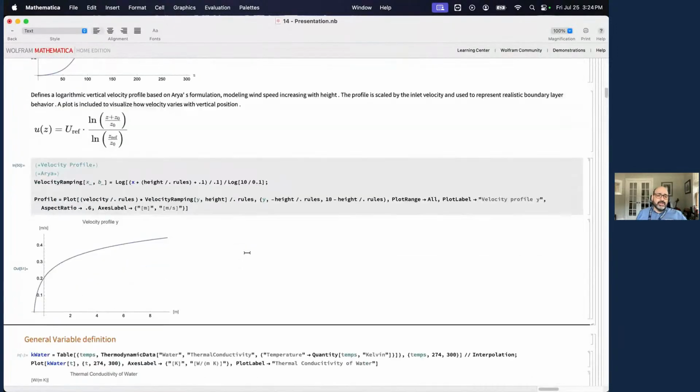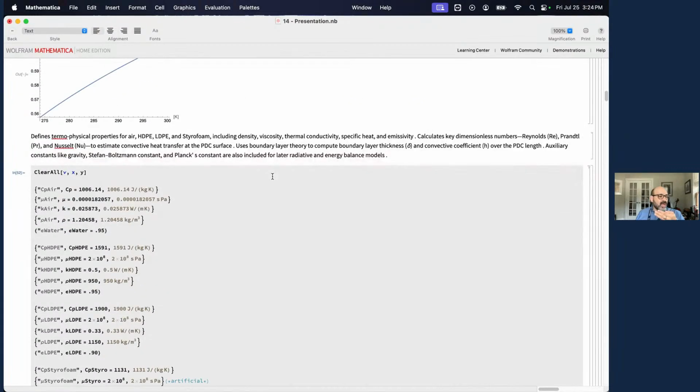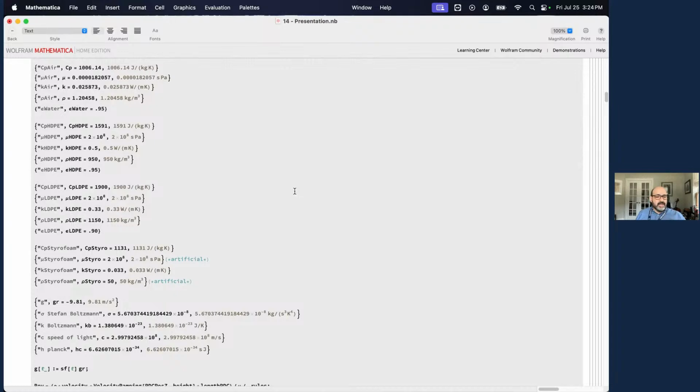Now, the other technique that I use is that I broke this down into several steps. First of all, solving the Navier-Stokes equation. Second, solving the heat equation. Third, solving the radiation, then solving the condensation. Now, you could do all of it at once in a single equation, right? That's a coupled solution, but guess what happens? It's going to take even longer. It may not solve, and it just becomes very complicated. So the solution here, and you'll see later, is that you solve one, inject those results into the next, inject those results into the next, and so on until you get your solution. And guess what? The results are the same.